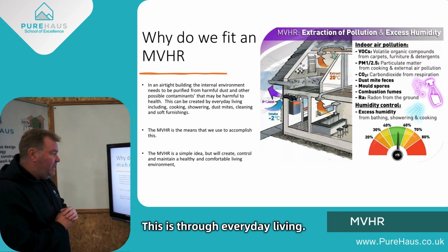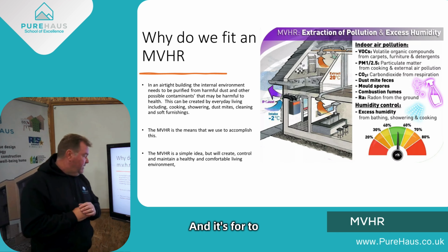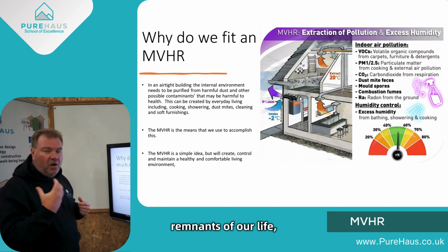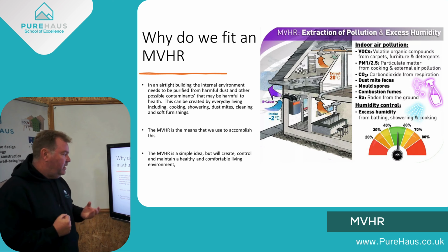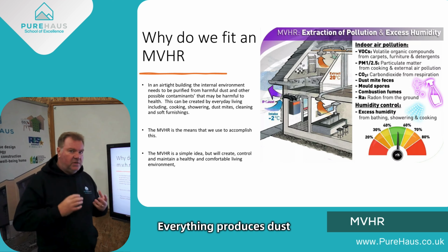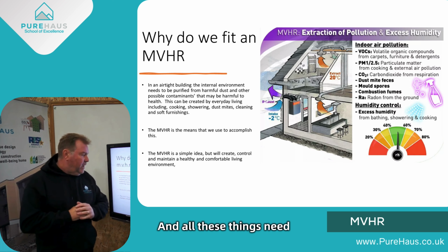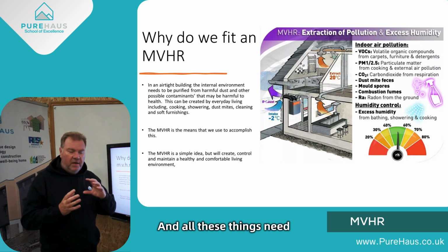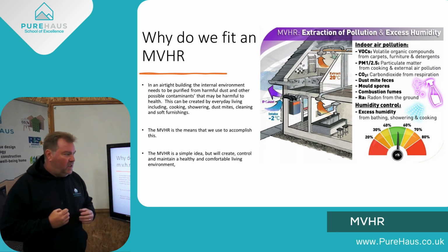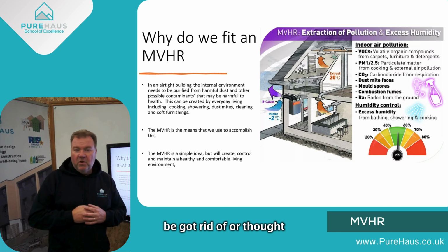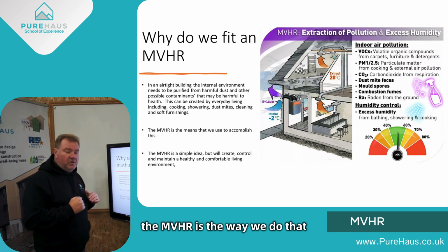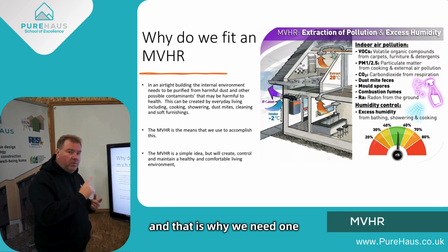This is through everyday living, and it's to get rid of all the remnants of our life, which is showering, cooking, cleaning, soft furnishings. Everything produces dust and dust mites, and all these things need to get rid of because we're in an airtight build. We don't want to live with those. So all these things need to be got rid of or thought about. The MVHR is the way we do that, and that is why we need one.